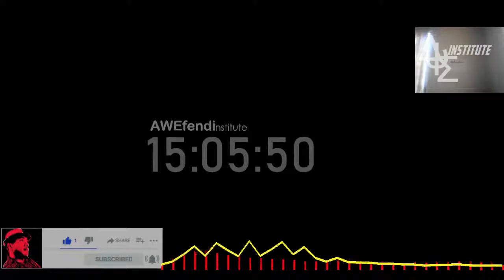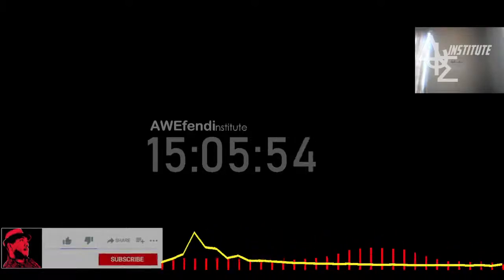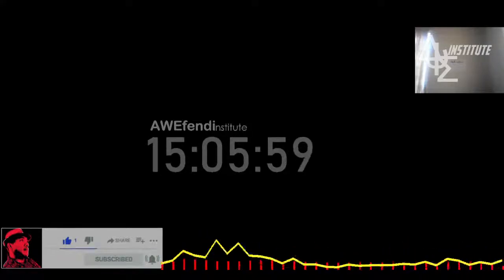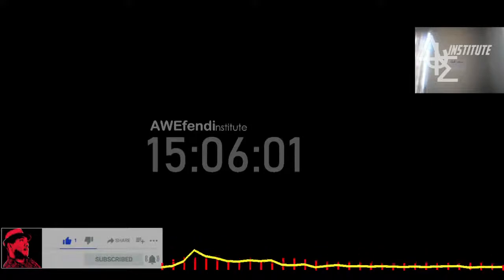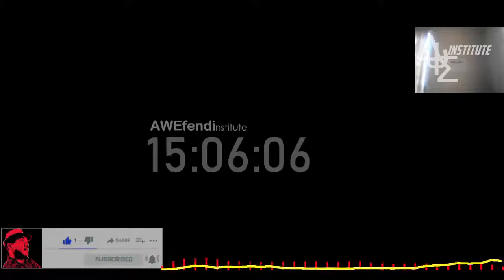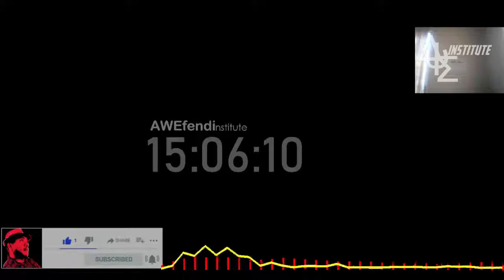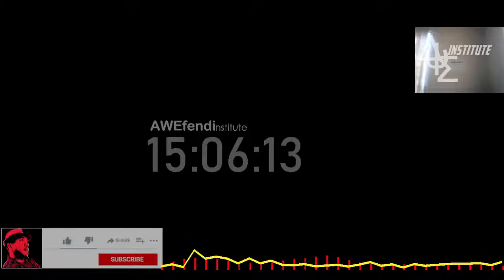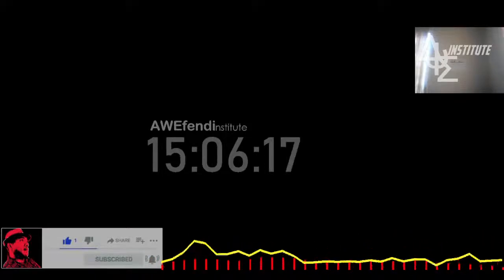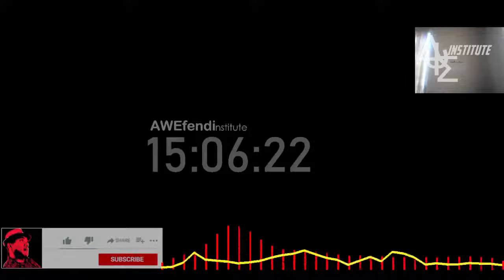Now, we're in Explore mode, so that's a live GPU solver. We're going to get almost instantaneous results. What we're seeing here are curved vectors, but sometimes the direction field is nice to see, for example. If I put it this way, you can get a little bit more information. You can see first of all your velocity magnitudes, and then overlaid on that the streamlines. See where you have the recirculation zones and whatnot.